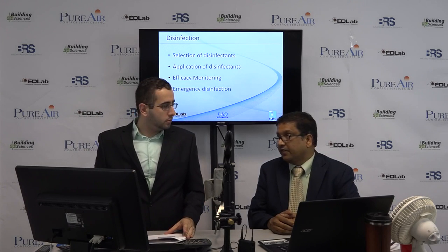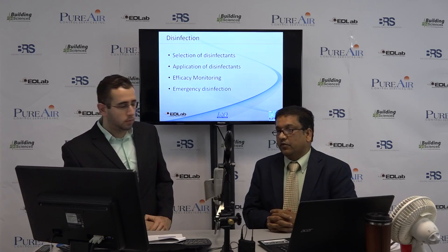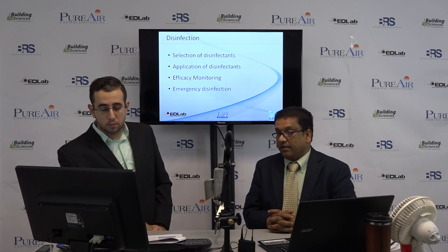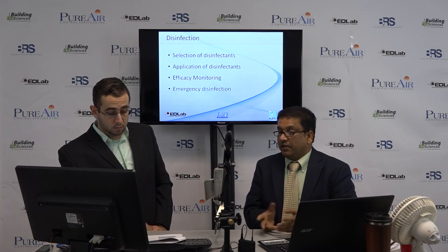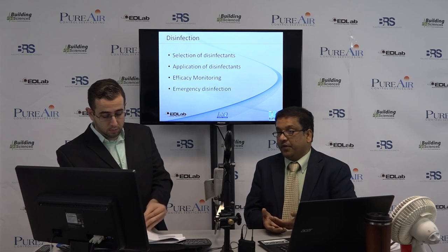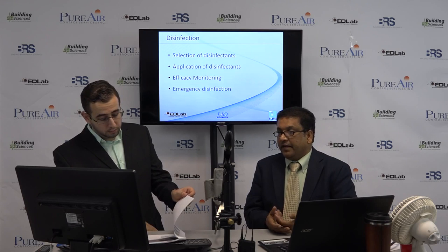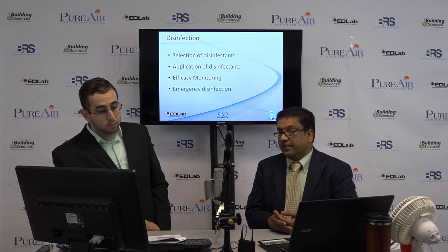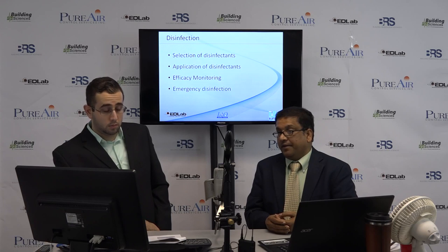So selection of the disinfectant is the main thing, because once you know what kind of method one should take, it gets disinfected. Nowadays everybody is going after green technology, and I support that, because there are several methods by which you can disinfect. The first method is that people use chemicals such as chlorine to disinfect. Then there is the heat method. The heat shock method is that you raise the temperature for certain hours, and the bacteria don't survive at those temperatures, so the bacteria are killed.